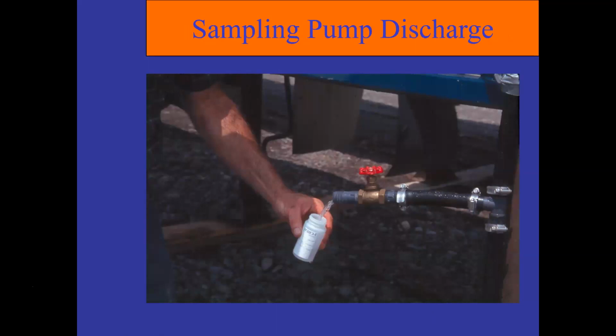So I'm getting a little nervous about this test. We're running this for 24 hours, and I never saw any red. So I kind of thought that somehow we blew it on this test. And it's one of the harder things to decide on, by the way, is how much tracer do you need to put in? Because there are factors that influence how much of it's going to make it through to the pumping well. Things like matrix diffusion. You might get a lot of diffusion of the tracer into the pores of the rock.